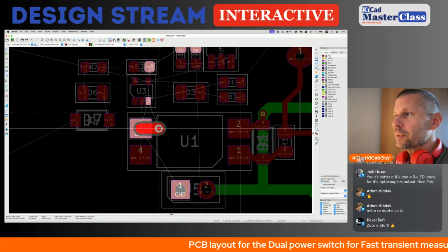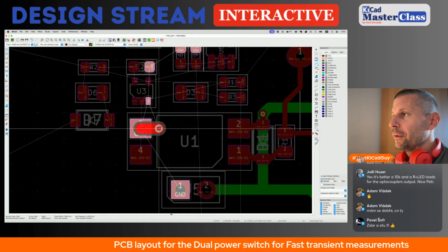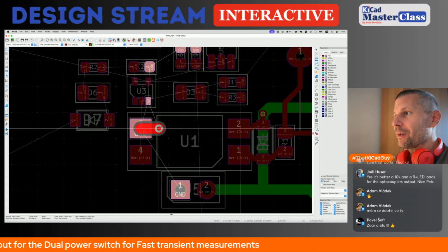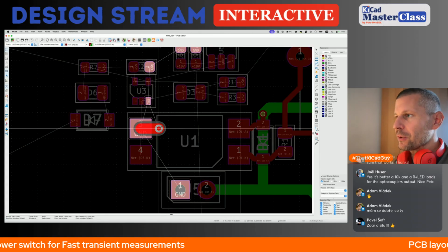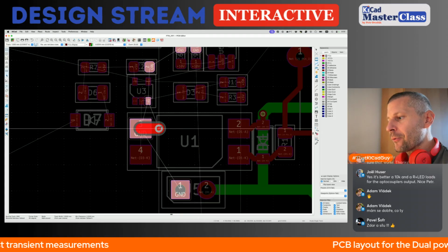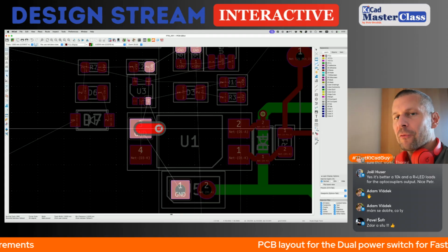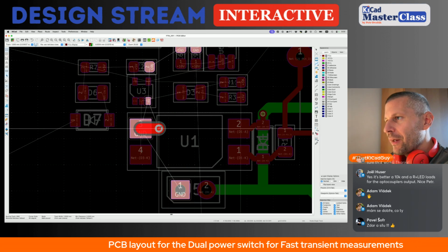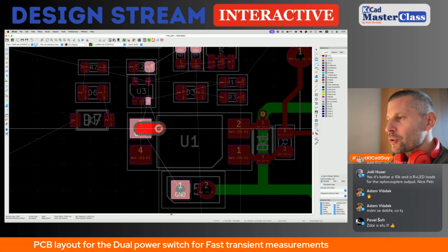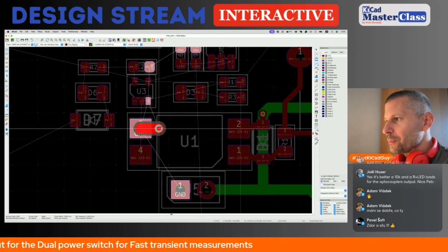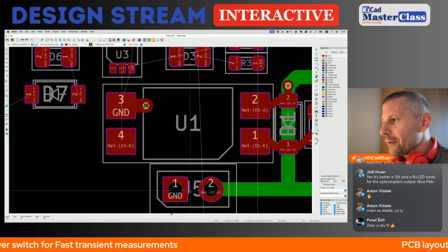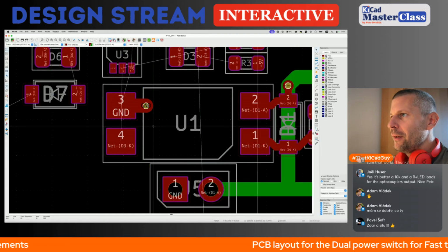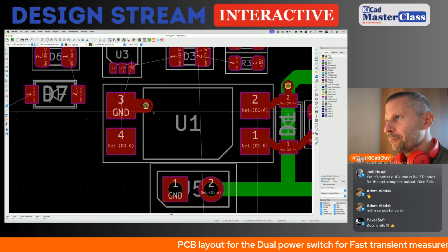As I explained, the reason for using the optocouplers is not to get some clearance, it's only the possibility to isolate the ground of the waveform generator from the ground of the instrument. So this way I can easily shorten the clearance between the inputs, because as you can see, the real clearance is the clearance of the jumper header, not the clearance of the optocoupler.